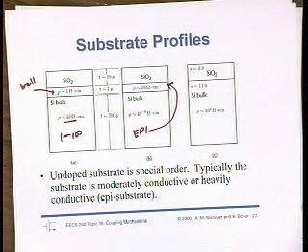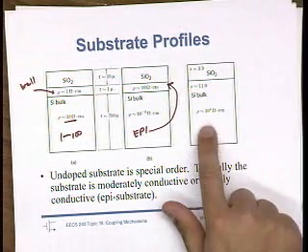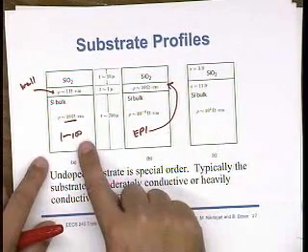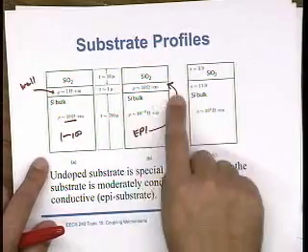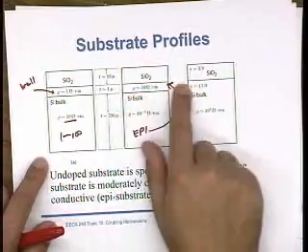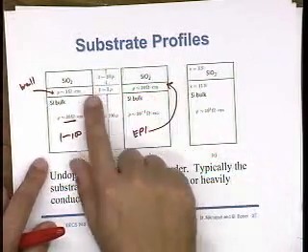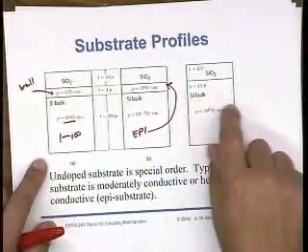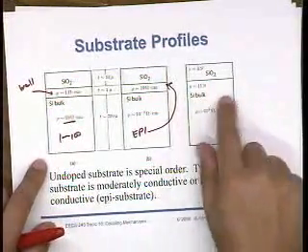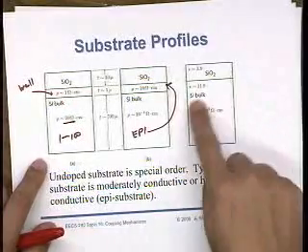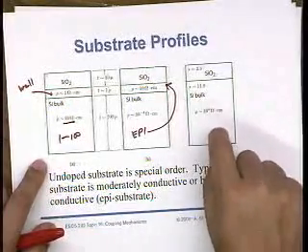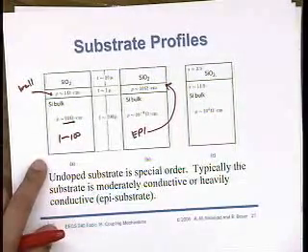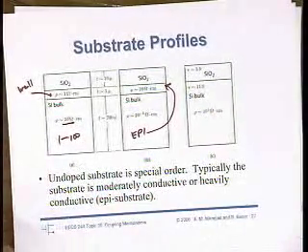But it's great for substrate isolation because if you think of this as a resistor, this is a dead short practically, right? This shorts every node of the circuit to every other node. This one has a resistance between each node. This one's almost an open circuit, so it's mostly capacitive coupling between different nodes in the circuit. And so this is the best for substrate isolation, but it's not used. You might see an academic paper here and there, but it's not used.